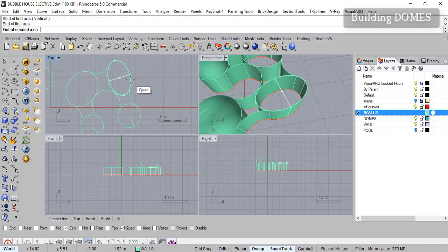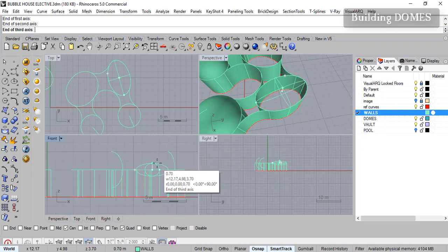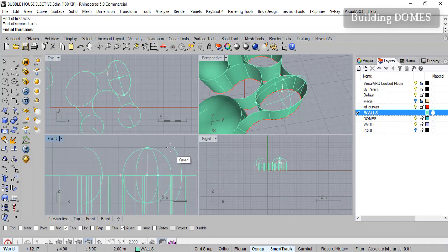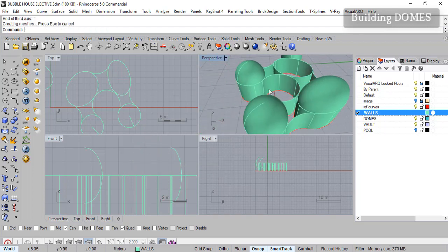So this is one diameter, and the other dimension is much easier to select in the plan than in perspective. With perspective you have a lot of circles and it jumps around the center points of them. So this is your first chord. We've just given the diameter dimensions, and we need to give a height. So we come here in one of the elevation modes, and I guess this is the height of the dome, so we'll have it approximately match up with that, like this, and we have an ellipsoid drawn.